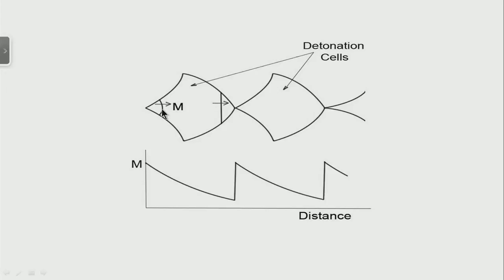Having seen that this is the structure by which detonation propagates, just to illustrate the three dimensionality, if I were to go to the previous slide and put a paper on this particular surface on which the signature could be written, the signature is not only in this plane which I am showing, but it is also normal to it. That means I get the pattern corresponding to the diamond structure, and within the cell of a detonation I start with a high Mach number.